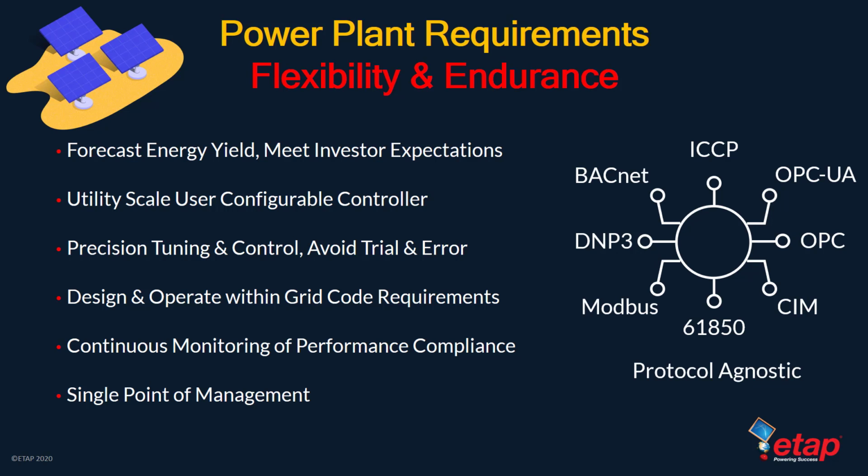for yet another reason. You run the risk of meeting grid code requirements during the design stage, but not during operations if you utilize a controller logic in simulation mode that is not commercially available to be used in operations. The cost to design, rewrite, and maintain two controller logics can delay commissioning and increase startup costs.